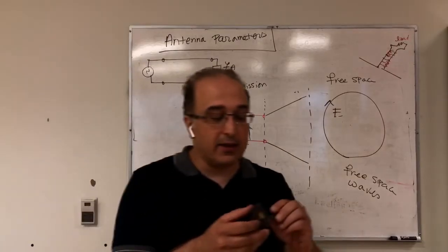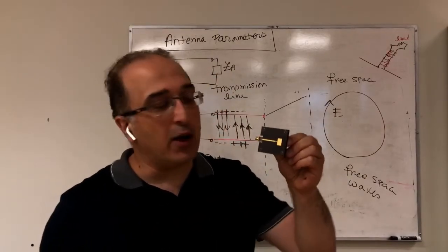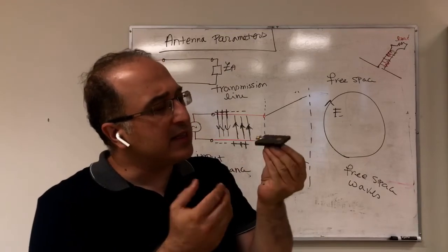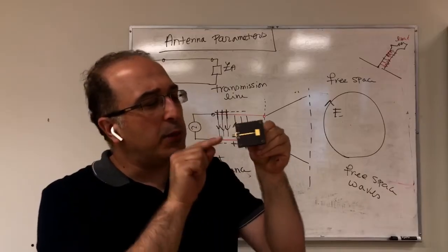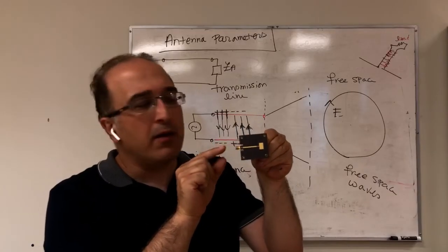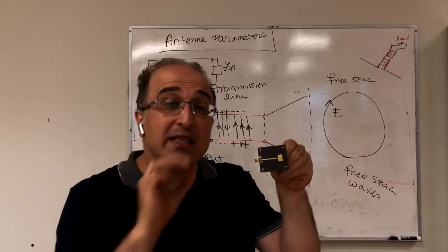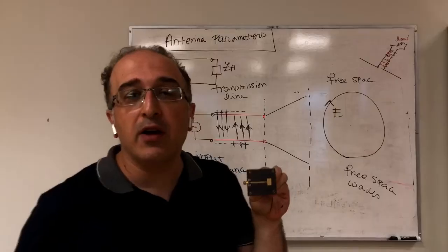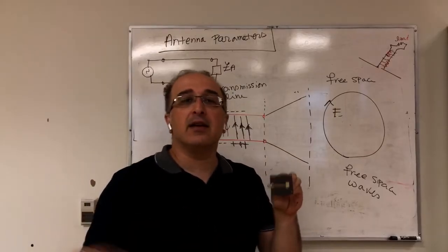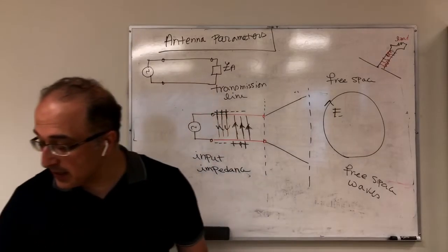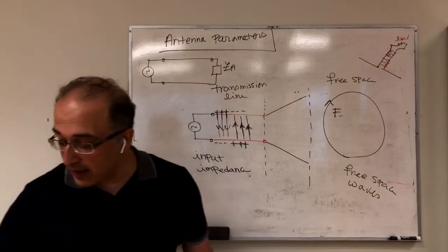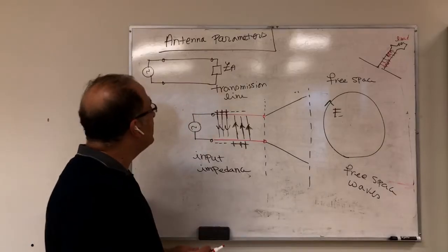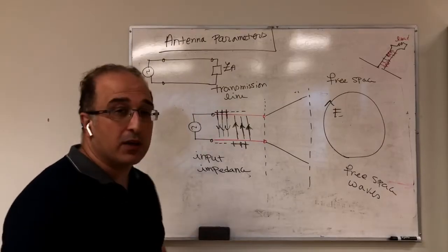That's another antenna, again from our measurement lab. So this is a microstrip antenna. So you see this has different components, but then the excitation port is here. Now, if you connect this to a circuit, from a circuit viewpoint you can remove the antenna completely and assume that you have a load with a certain input impedance here. That's extremely important and such a powerful concept. So this would be our input impedance of the antenna.